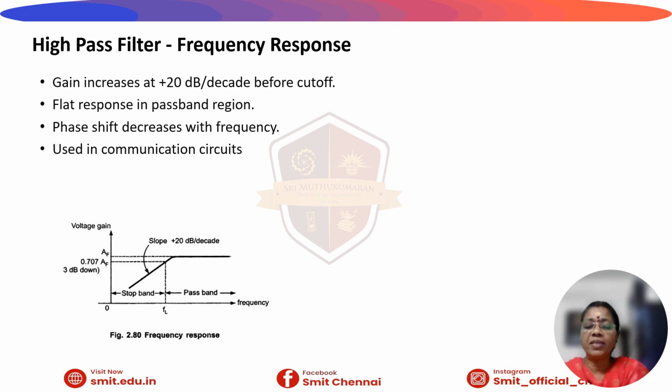The phase shift is such that the output signal leads the input signal. At the cutoff frequency, the phase shift will be plus 45 degrees. It is used in communication circuits, audio tweeters, AC coupling, and vehicle equipment.